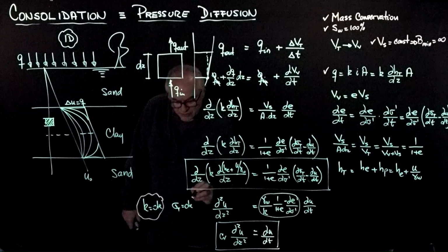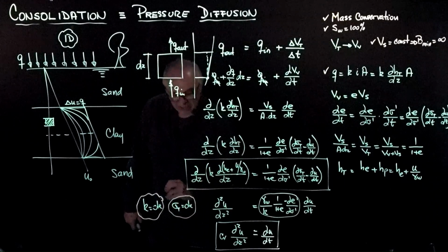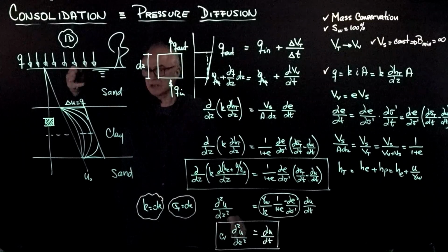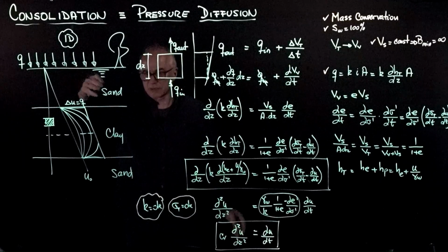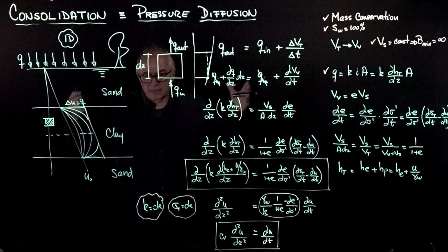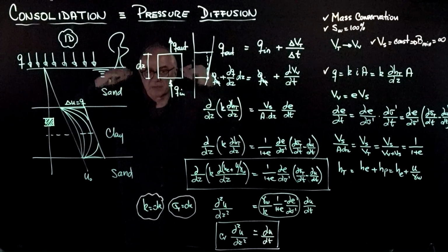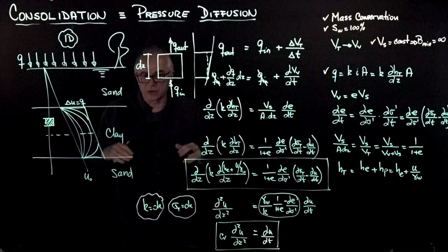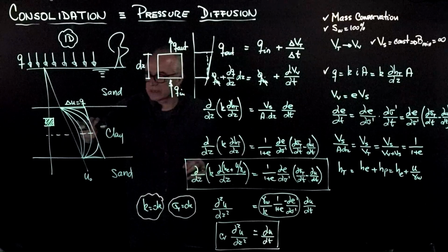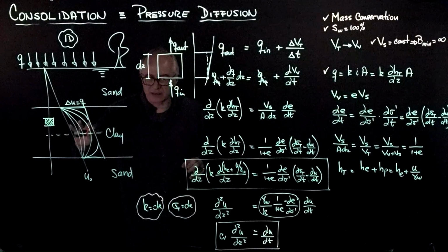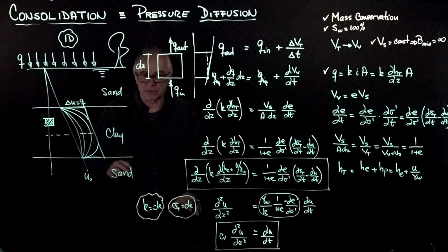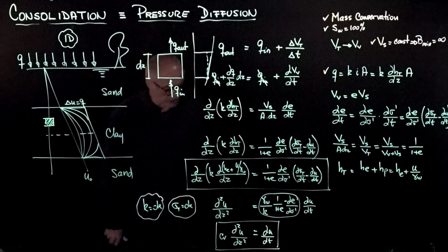And we are assuming that the load was instantaneously applied and that it remained constant thereafter. And that may not be the case for your problem. For example, you build a dam gradually, or you make a building foundation and then we gradually build the different floors and apply the load. And that time scale of loading may interact with the time scale of the diffusion process, and you cannot separate them in taking this extreme. You will have to keep it into the picture.